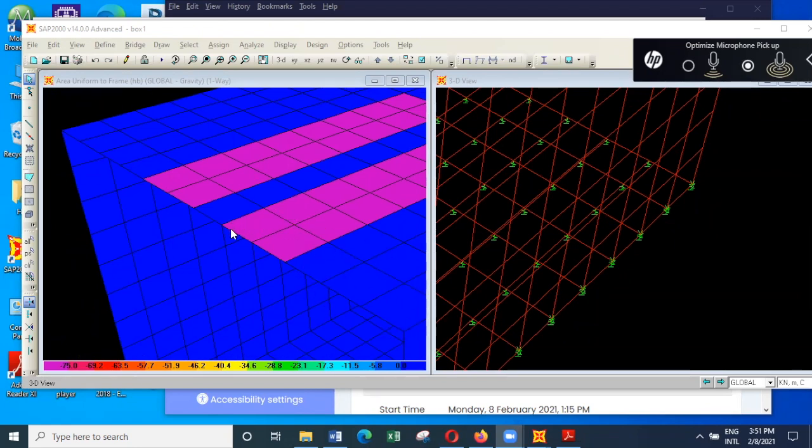So I have considered that this is the center, 2, 4, 5, and the load has moved past the center by 0.5 meters, so that the resultant will act somewhere here. The load will act here, so that I will automatically get something close to the maximum.